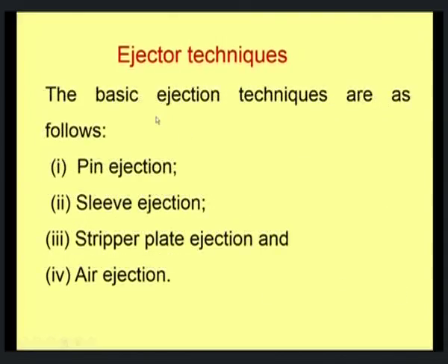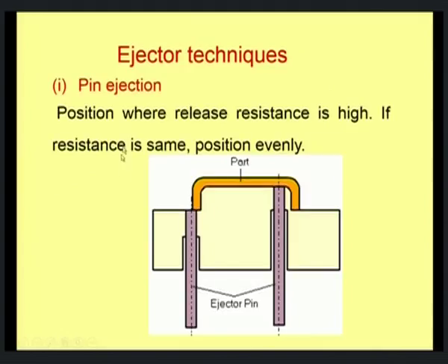Now, there are a number of ejection techniques, but these are the basic ejection techniques: using a pin or using a sleeve or using a stripper plate when the product is of bigger size, and apart from this, compressed air is also used to eject the product out. We will see one by one. So, in the pin ejection, these are the ejection pins.